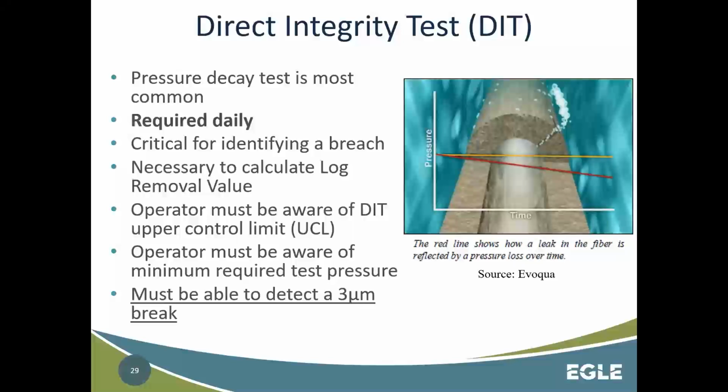And in that settling basin, you are removing the majority of your turbidity. And then from there, it goes on to filters and gets polished, we call it. It's kind of that last bit of turbidity is removed. And then it's disinfected. And so you have all of that turbidity removal and that settling happening in that settling basin.